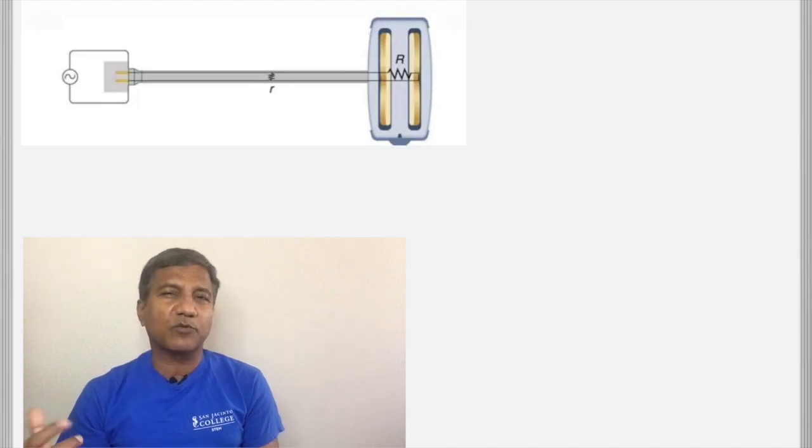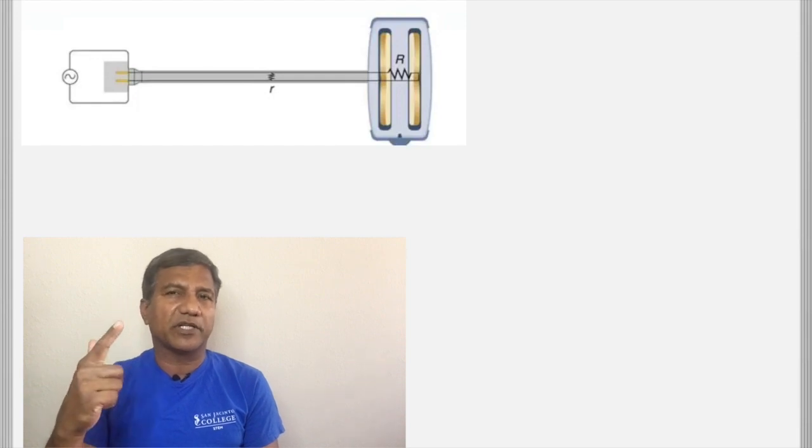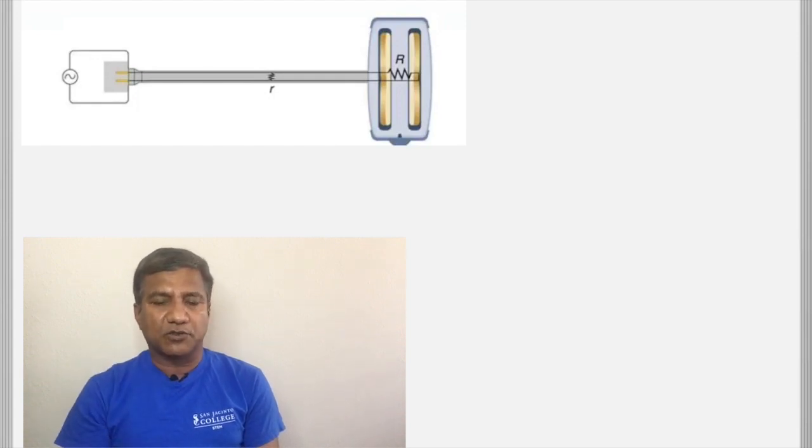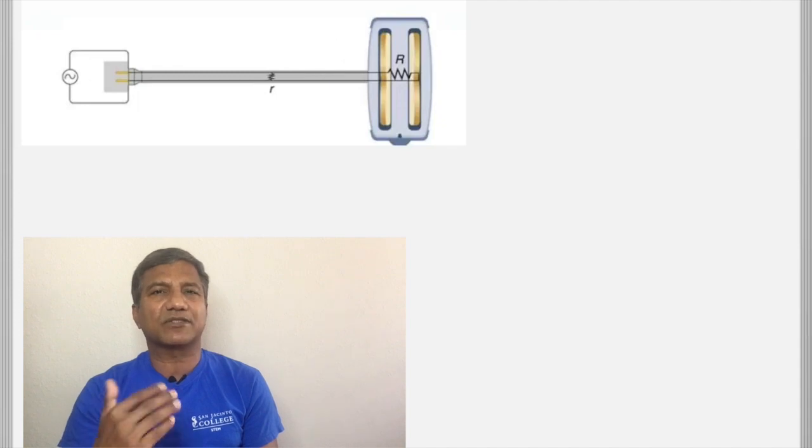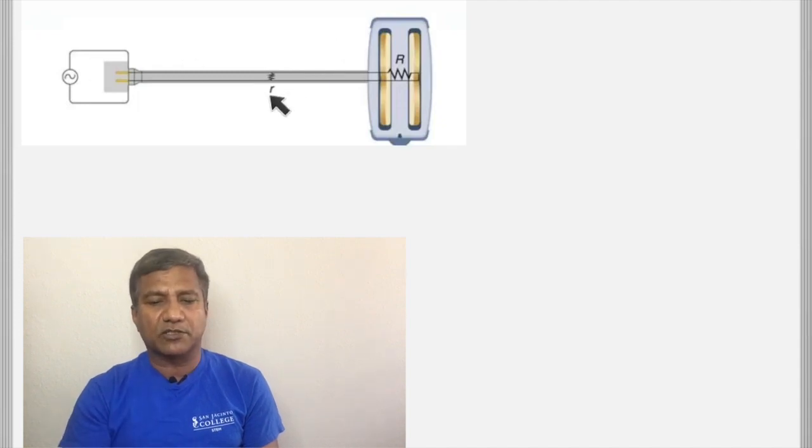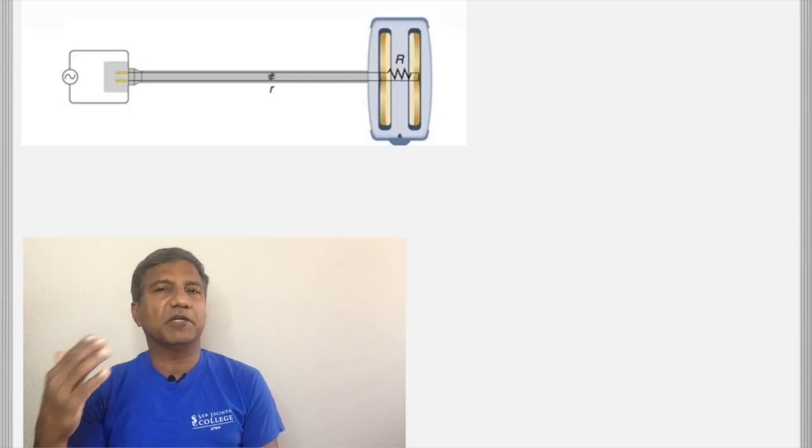It may be that one part of the conductor is touching the body of the equipment. Current always chooses the lowest resistance path. So instead of going through the whole equipment, it will take the shorter path now. The shorter path has a much smaller resistance, and when the resistance is small, the current is going to be really big.